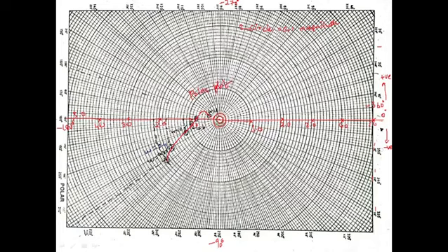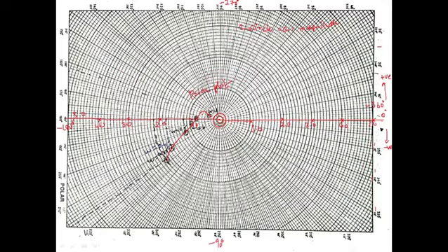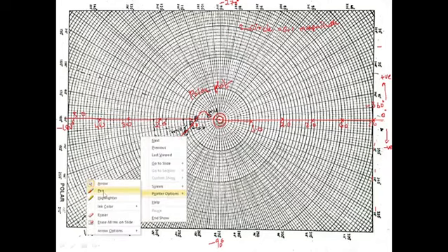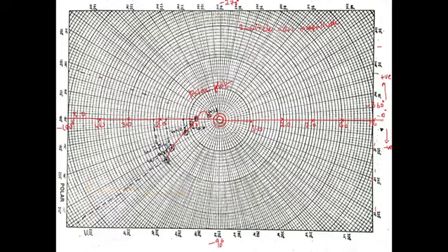Now, after this, we have to find two important things. What are they? One is called gain margin, another is called phase margin. So what is gain margin and what is phase margin? First you will find out the phase margin, and we will go for the gain margin later. Phase margin involves the polar plot and the unit circle. You know where the unit circle is, right? The unit circle is the circle drawn with radius 1, right? So this is the unit circle.